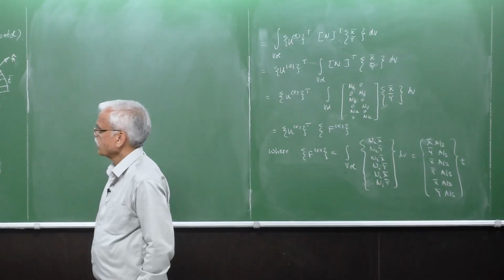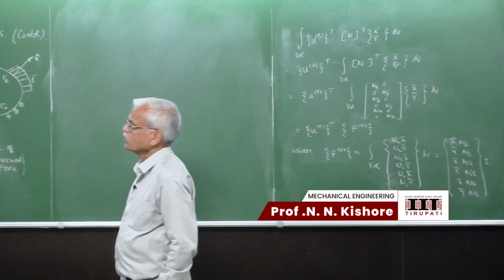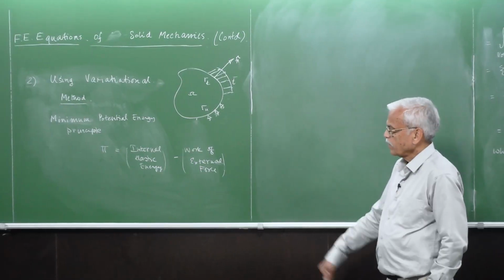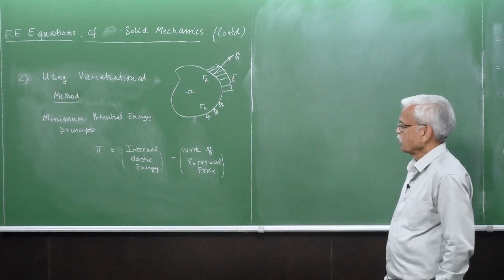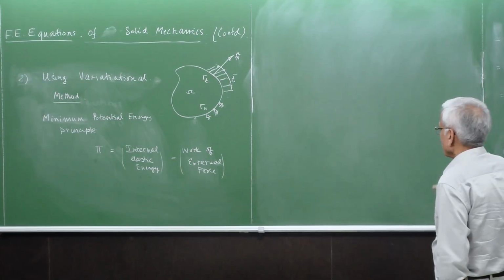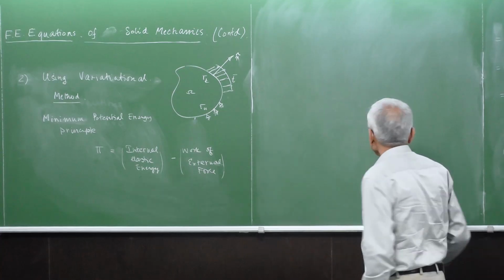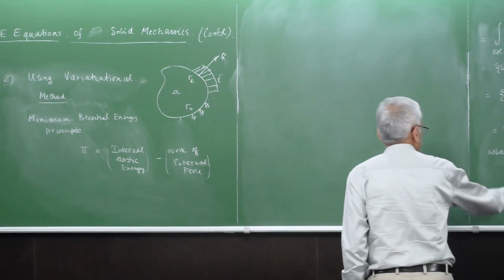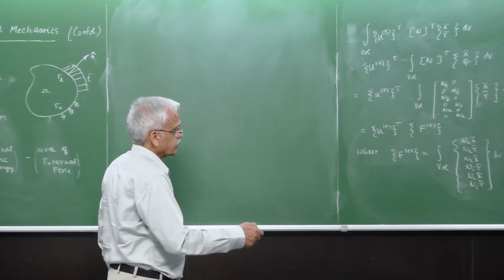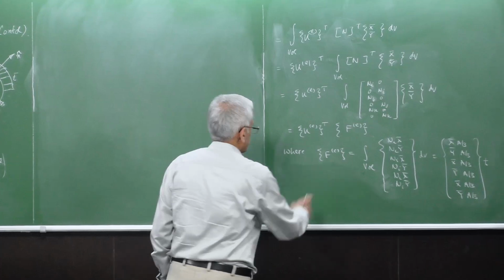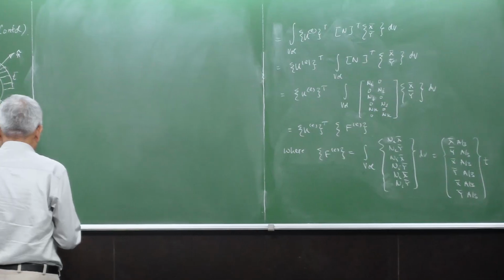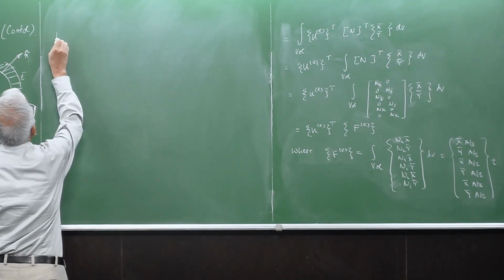Good morning. Let's continue our discussion on the finite element equations being developed for 2D solid mechanics and 3D solid mechanics. So we have formulated the potential energy, which is in this form, for the triangle, where we found out the stiffness matrix, as well as the nodal load vector. So if we collect these things, so the potential energy